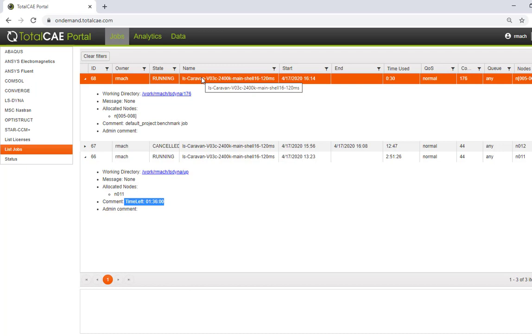Now you can totally control everything on this job list. I can actually cancel it. I can choose to set jobs at different levels of priority if they're queued. I can also have application-specific integration, like these ascent switches, which tell LS-DYNA to choose specific actions when we enter them. So depending on the app, you'll see different menu items that let you contextually do things that application has in terms of controls.